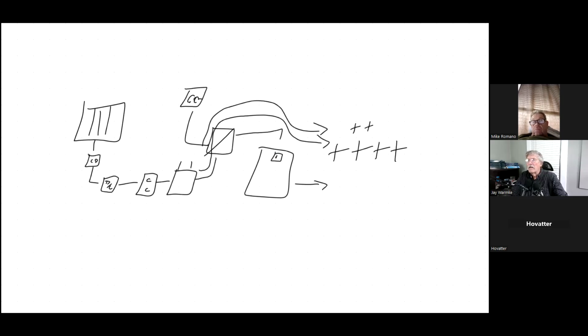It doesn't matter if there is a solar array there. The solar array's function is to take power from the sun and recharge the battery. So think of it as a firewall somewhere in the middle of the battery. The array is sized to charge the battery. The battery is sized to service the loads. Each one can function independently of the other.